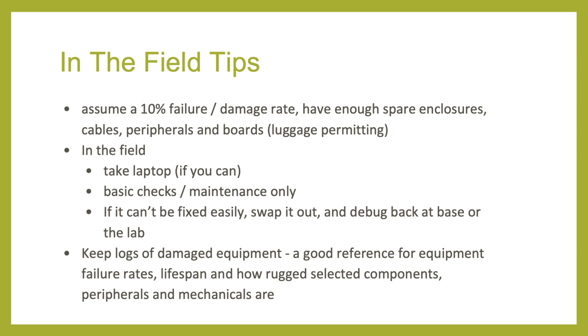Throughout the deployment, we'll also mark any damaged equipment with a red dot sticker and keep a failure log of which device it was, what failed, when, why, etc. The failure log is good because over time, we get a good picture of the lifespan of the device in general and the durability of the parts and enclosures we've selected. For example, if we find a particular temperature sensor fails quite a lot, we can try another one from a different manufacturer. Or if our enclosure wears and weakens too soon, we can look at a different enclosure and mechanical